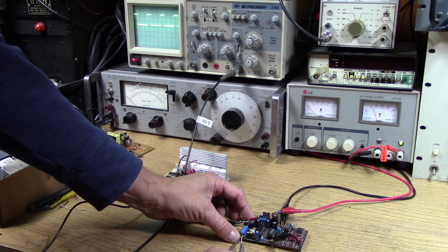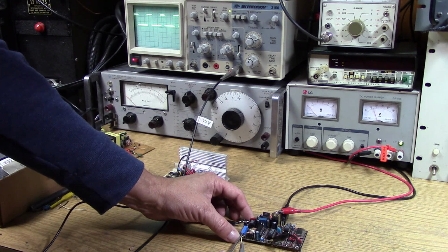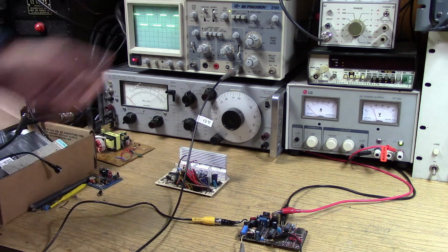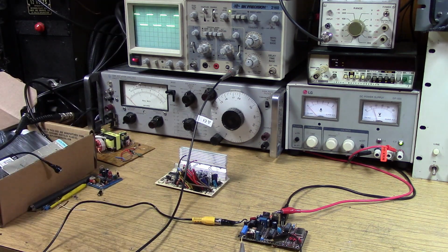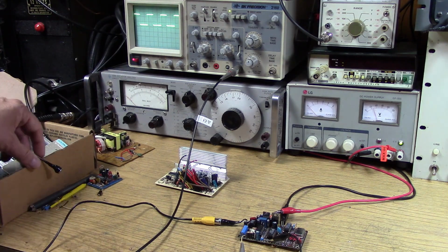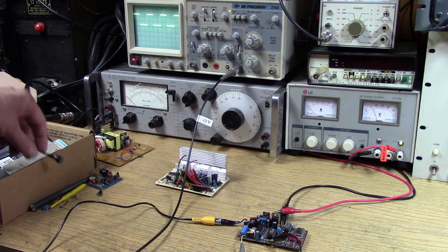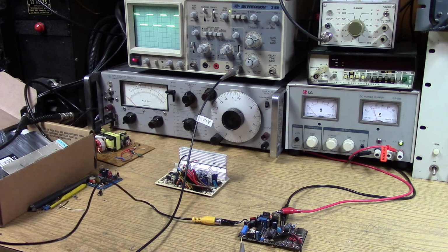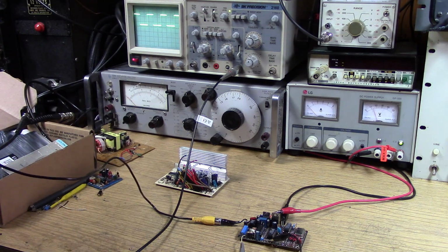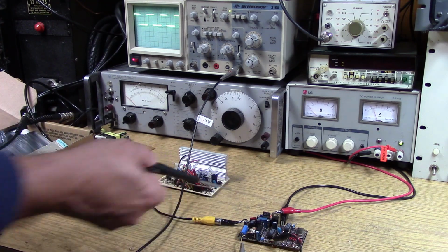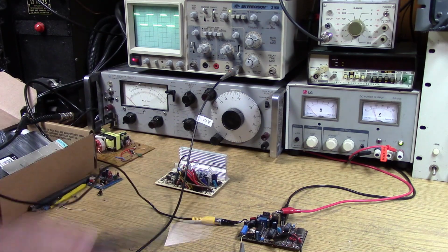It turns out that for AM modulation, similar to a Class D audio amplifier, you want to set it for approximately 50% duty cycle, or 50% mark space if you're old-fashioned. So once we've got this set up for about 50%, now you can see the modulation occurring on the waveform. Also, I put the 741, or actually another 741, in.